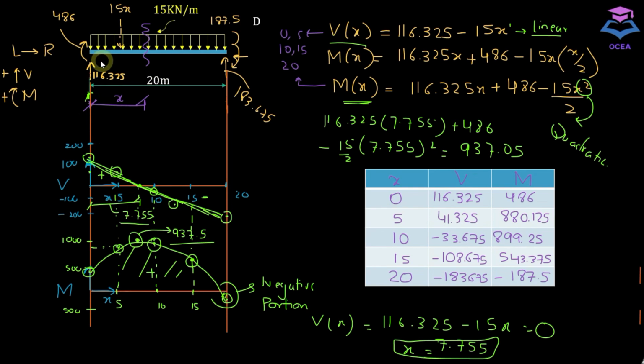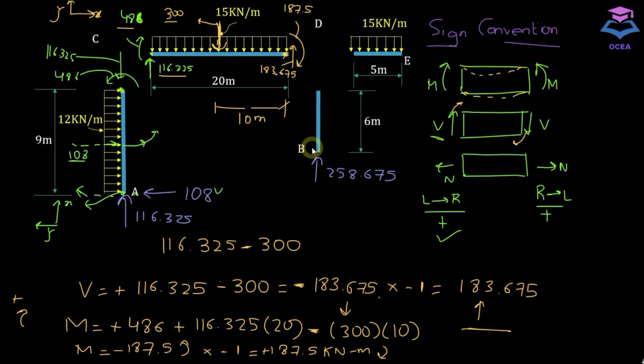We can see that in this member there is no axial force compressing or elongating this member on both ends. So the axial diagram will be a 0, 0 line for this member. This is the axial diagram. Using the same procedure and method, diagrams for DB and DE members have also been plotted.